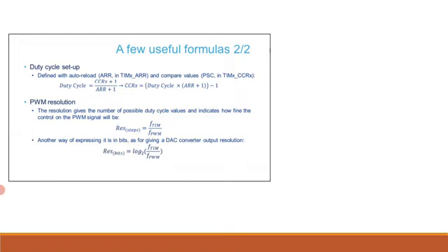The duty cycle does not depend on the PWM frequency and is given by the compare value plus 1 over the auto-reload value plus 1.